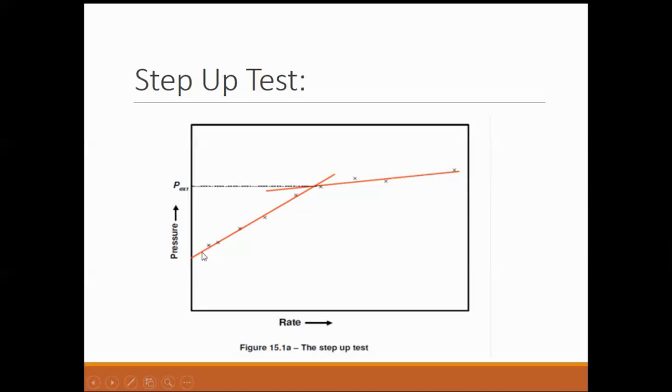So all these parameters come into play while deciding what kind of proppant size should be pumped. Even in tight oil and tight gas, which are extremely tight formations, generally the 16/30 or 20/40 sands do, because if you go higher than that size, the chances of crushing increase. So there are methods for calculating, with different curves. I cannot show them to you right now, but maybe we can take it up in the next session.